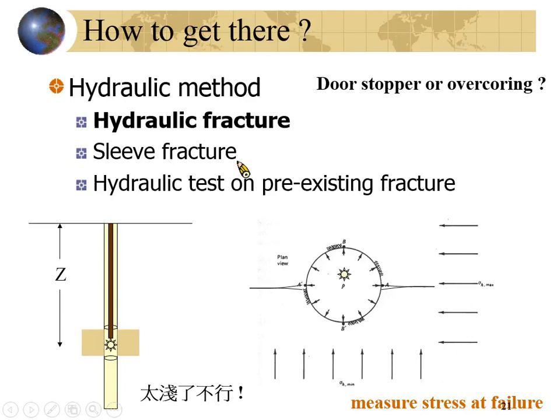So for this kind of technology, you need to have a free surface to measure, like a tunnel wall or like a shaft wall, like I mentioned to you. You need to get to where you want to measure the in situ stress, and you need to have some equipment there. So you cannot use it in a borehole. Understand? So that is what I always remind you: how to get there to conduct your measurement. It will be a very important point. Okay?